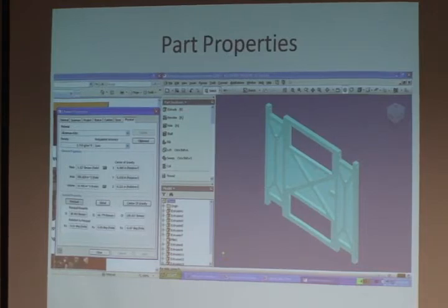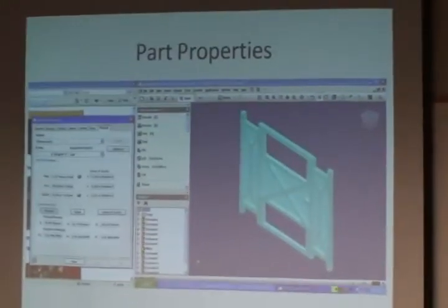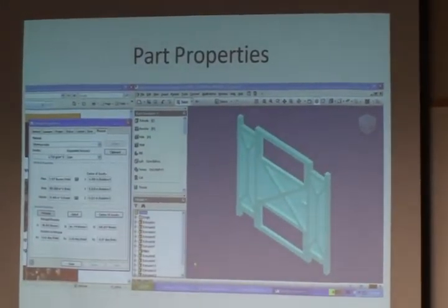Can we ask, how many of you are using solid modeling programs for doing this stuff? So the majority? Okay, so you're familiar with these things. Like Mike said, if you're using a battery and there's no setting for battery, what we would do is draw a block with the dimensions of our battery, and then assign it a weight. We'd weigh the battery and then assign it that weight. These things are surprisingly accurate also. They're pretty darn close to dead on. If you're using a certain grade of aluminum, it's pretty accurate.